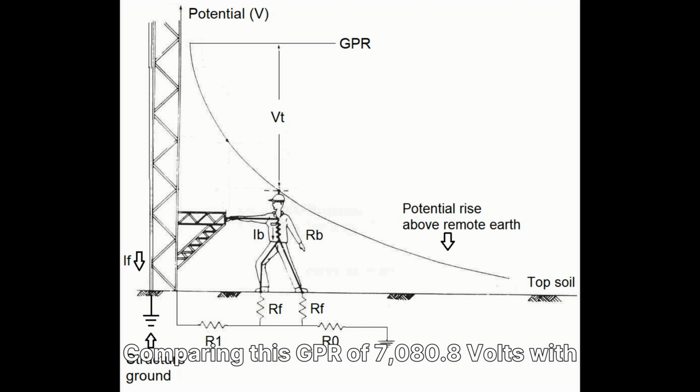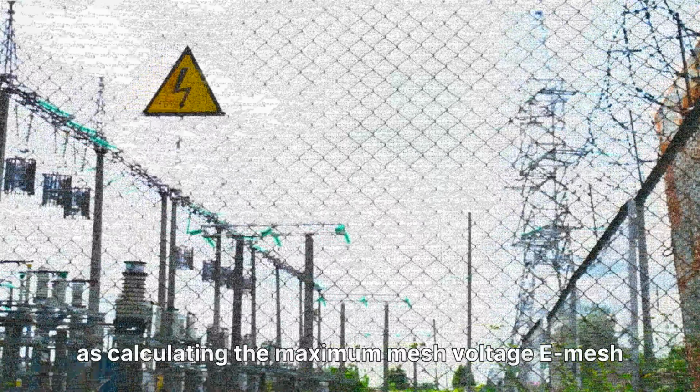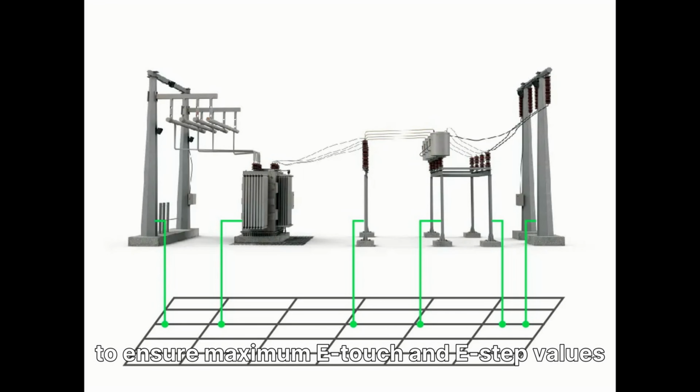This indicates that the current design is not safe yet, and further analysis, such as calculating the maximum mesh voltage, is required per IEEE 80. Such situations necessitate a redesign, perhaps by expanding the grid or adding more conductors, to ensure maximum E-touch and E-step values stay within tolerable limits.